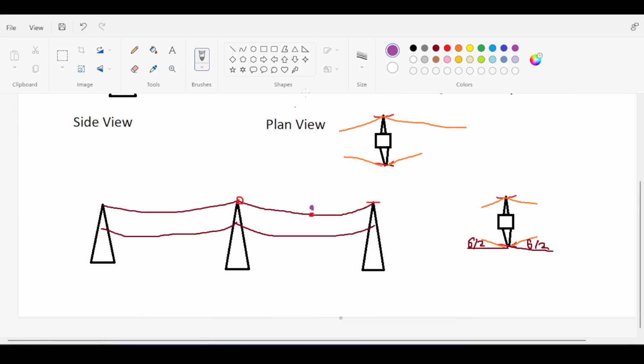So somebody else would say, well, what about calculating the top of the cable here and the top of the cable here, or basically one top of the cable, and assume it to be the ruling height here. Each cable has one top, so you can basically calculate the wind load on each cable. Now, this is more of a hassle. It's correct, but what the ASCE code does is it takes the tower.